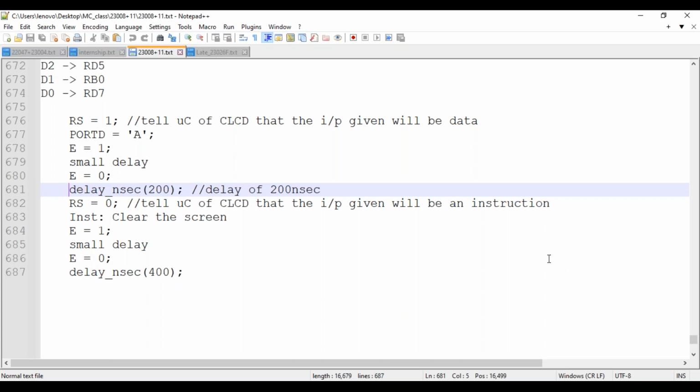Then whatever we wrote previously from seeing the data sheet, like the instructions, is only to set it to 8-bit mode, 5 by 8, and to turn on the CLCD. It's common every time, right, like the driver code. And if we want to write data by setting RS equal to 1, we can write using the function you are telling now. Am I correct? Yes, it is.